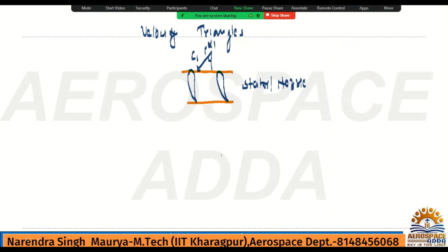Now this flow will have a relative component as well as an absolute component. Because the rotor will recognize only relative velocity, for that reason you have to be aware of the relative velocity, because for the rotor relative velocity is important, nothing else, as I told you in compressor also.